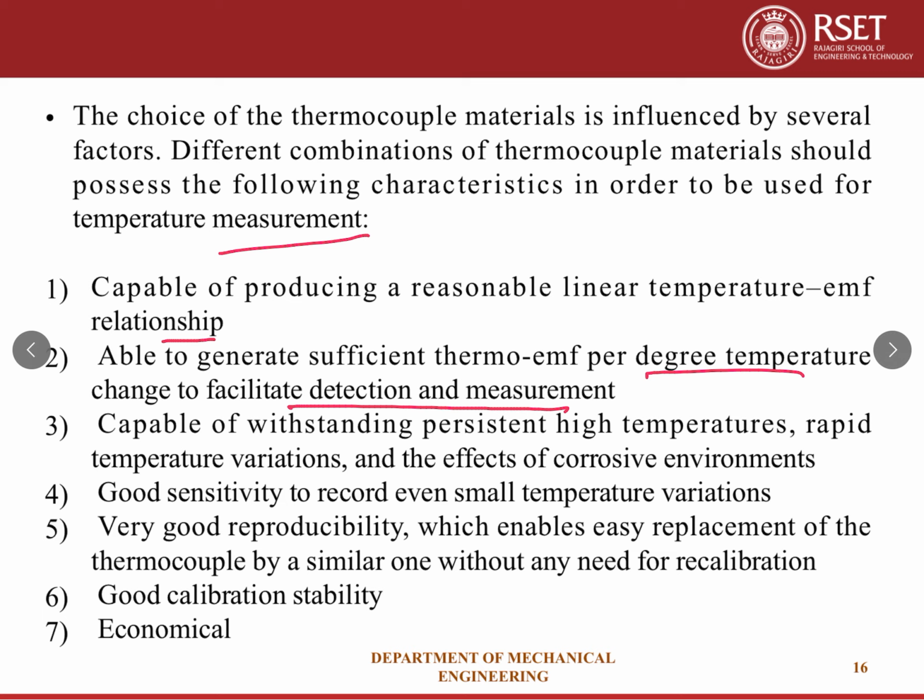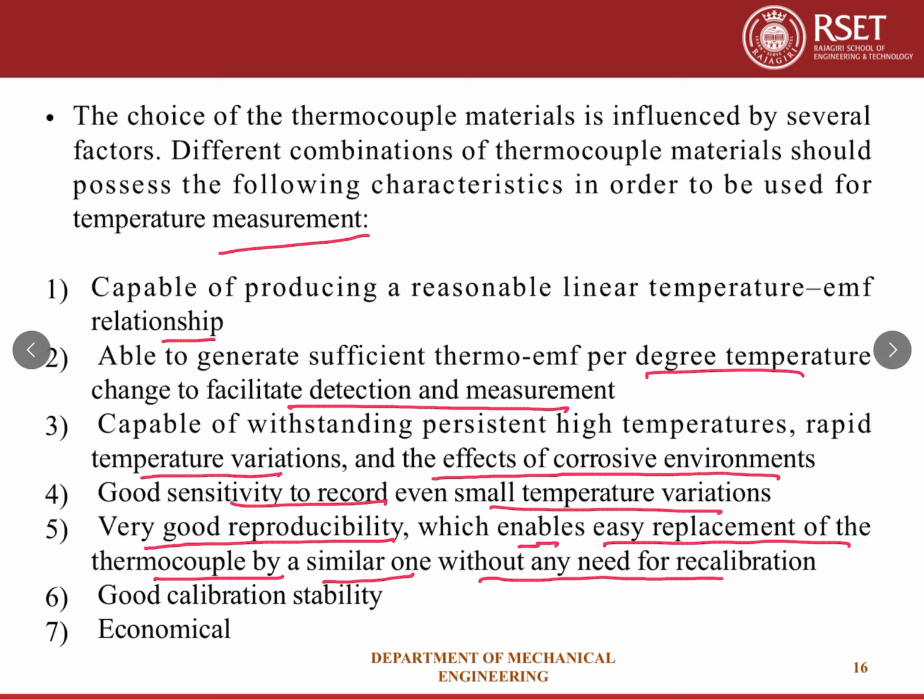Capable of withstanding persistent high temperature, rapid temperature variation and the effect of corrosive environments. Good sensitivity to record very small temperature variations. Very good reproducibility, which enables easy replacement of a thermocouple by a similar one without any need of recalibration. Good calibration stability, and economical. Many of these factors need to be considered while selecting a material for a thermocouple, and we found that there are different base metal types and rare metal types. So that's about the thermocouple materials.